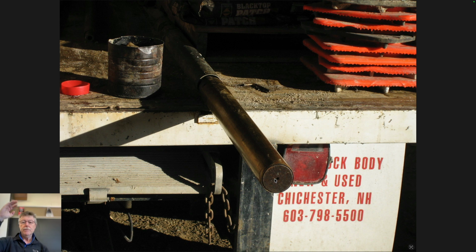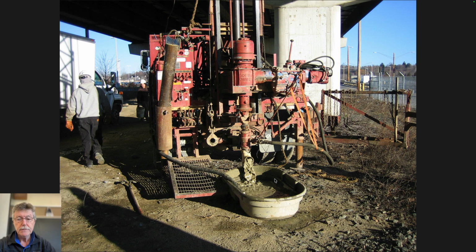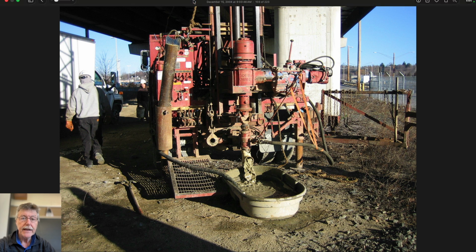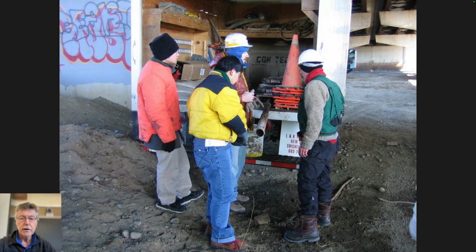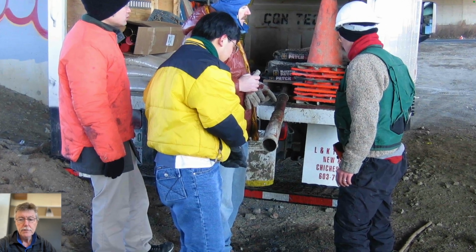And then when you pull it up, you keep the vacuum on it because there's no airspace, and bring it up to the surface. So all this contraption is taken off. It's advanced down this empty hole. Actually, you can see this is the same as before. This is the return drilling fluid. This is the drilling fluid being taken out of the tank and being passed up into the gantry and then going back down. A bunch of people mulling over exactly what to do with the Shelby tube.